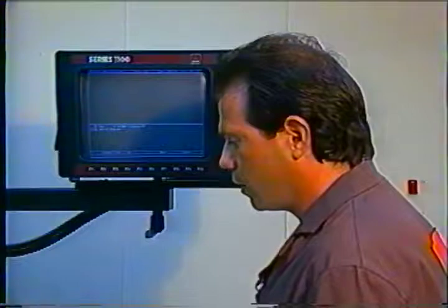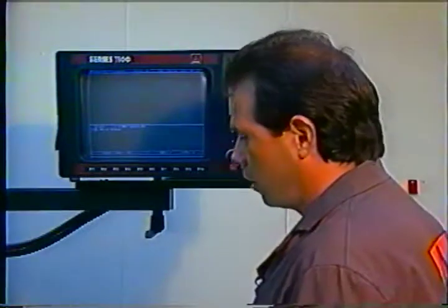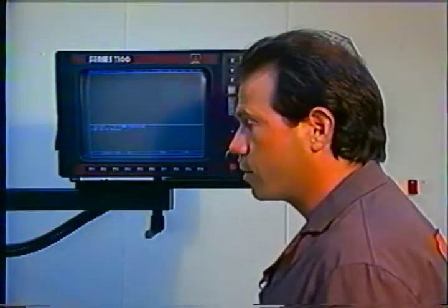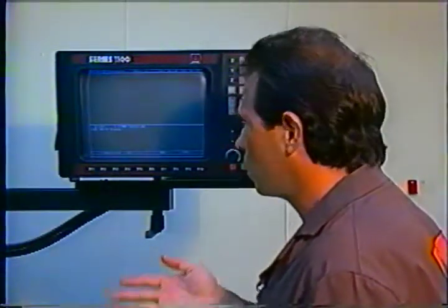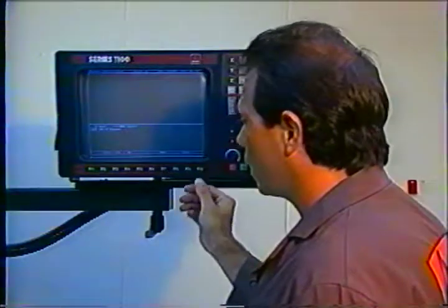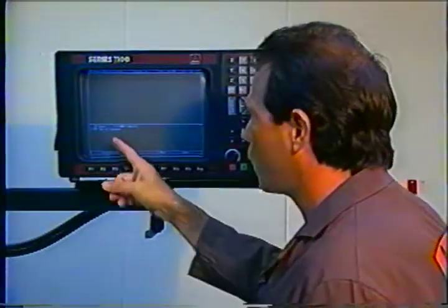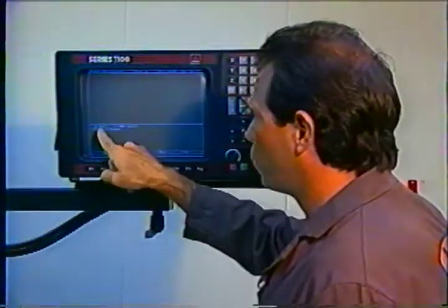So I've fulfilled all the needs of cutter comp, turning it on in a correct manner and turning it off in a correct manner. Now, the next logical step in the program would be to cancel the tool and raise it up to home position. So I'll select Rapid, Z0, and Tool 0. And then I'll make my modal move, which is just simply an X or Y move with no rapid or line designation. It will be rapid since the last move we input is rapid.